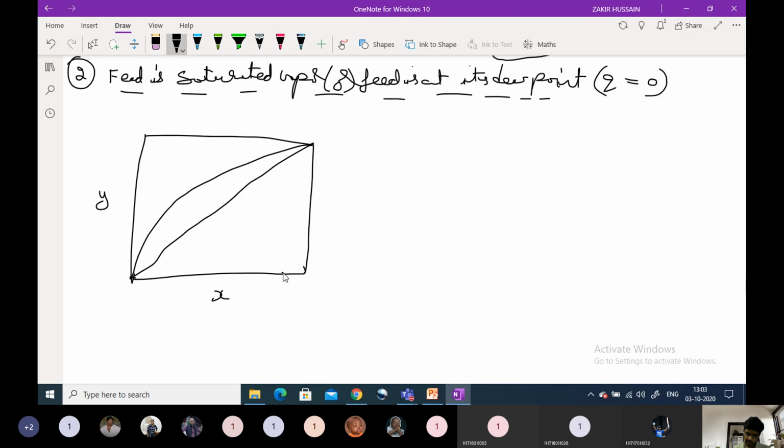Before deriving any plates, first we have to locate our xd value and project it up to the diagonal. Then we locate xf and project it up to the diagonal, then xw. All three compositions we know.